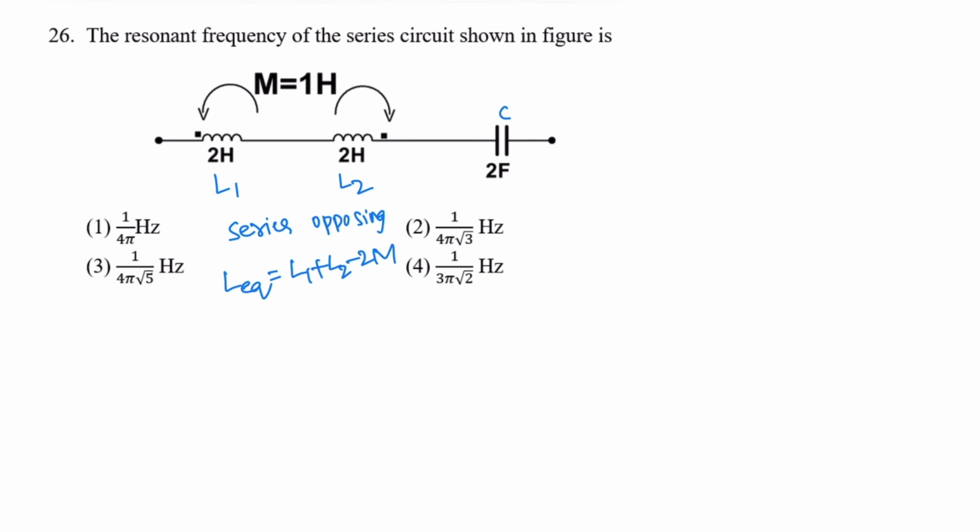When inductors are connected in series, the magnetic flux of one inductor links with the other inductor. The magnetic coupling between the coils may either increase or decrease the total inductance. The effect of mutual inductance depends upon the coils and their orientation. If the magnetic fluxes of the coils support each other, the connection is called series aiding. If magnetic fluxes oppose each other, then it is series opposing. The direction of the current entering the dot end of the coil determines the polarity of voltage at the dotted end of the coil.